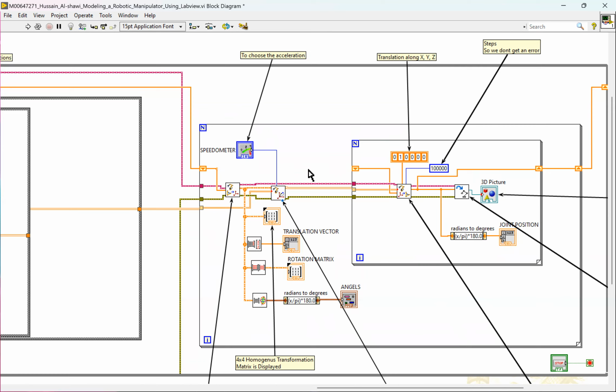Okay, these are the DH parameters, these are the joint angles, this is a button that's being pressed. Where do I need to be? Where does the end effector need to be? So this is what the inverse kinematic block does. Now obviously we have to update the plot before visualizing it, and then we use a 3D picture to visualize it.